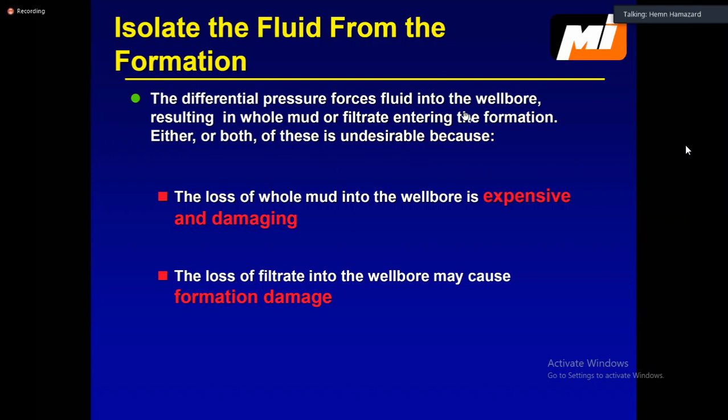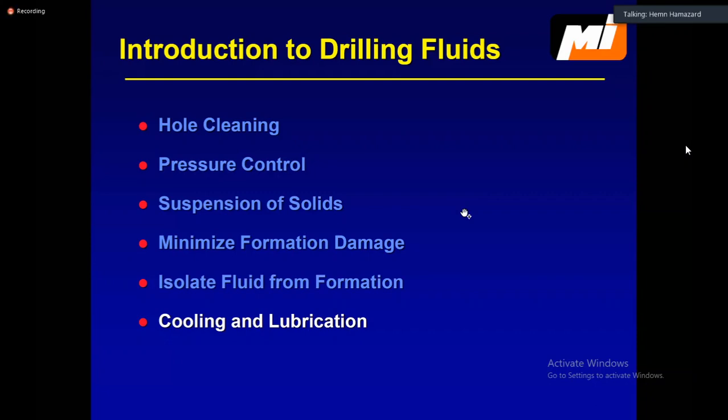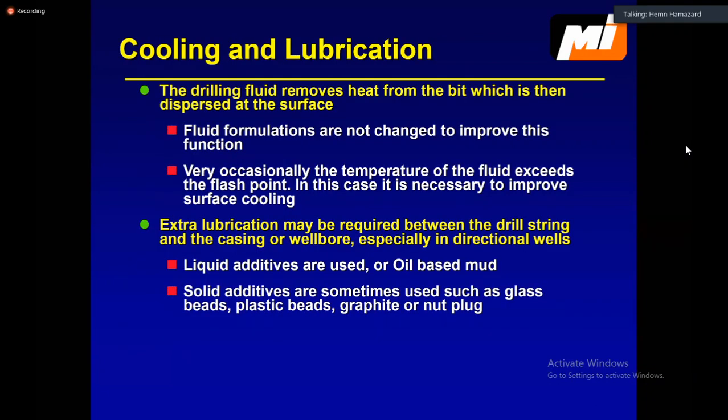Another point in here is we discussed this, cooling and lubrication. As you know, we have a lot of lubricants, especially we discussed yesterday. One of the systems of the mud is oil-based mud, or even if you have water-based mud, if you have some lubricants in your system, in your mud, then it can cool and lubricate your bit first, because the bit, like I said, is the first thing which is crushing or grinding your rock. And the deeper we go down, the harder the rocks become. Especially some rocks like limestone, anhydrite, dolomite, they are so hard. When your bit is crushing or grinding it, it creates a lot of heat. So the mud can cool and lubricate your bit first.